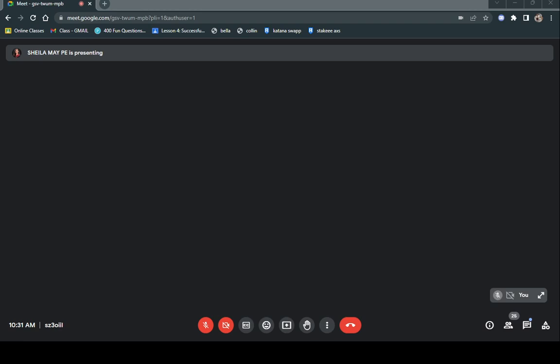But they're the same N channel. And for the arrow, that's pointing inward, so that's N channel. And for the P channel, that's pointing outward. Okay? And the gap here means our gate terminal is insulated from our N channel or P channel.